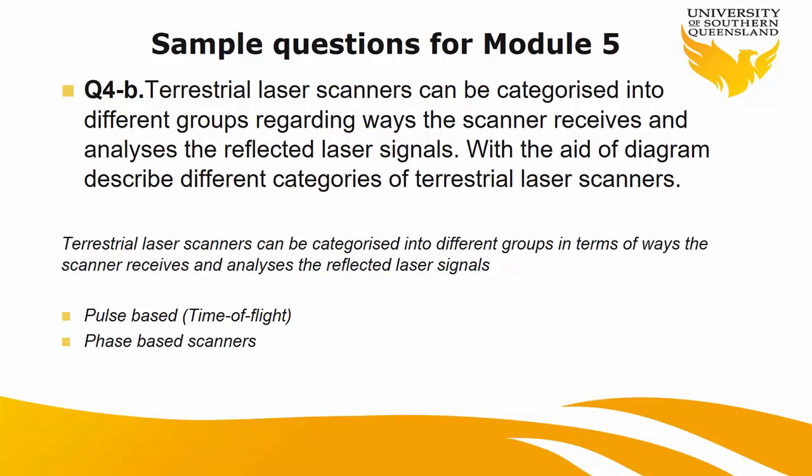So what type of question might I ask? I might have a very simple question like how does it work? You remember we had two types of laser scanning? It's very similar to total station. Time of flight, phase shift, do you remember that? One of them is measuring the travel time to find the distance. The other one is measuring the phase difference.